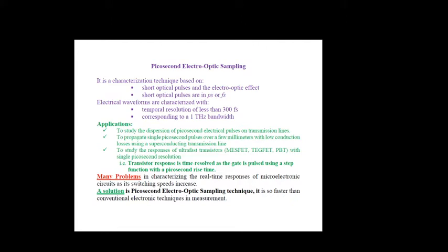Additionally, ultra-fast transistors have been tested with single picosecond resolution. That is, the transistor response was time resolved as the gate was pulsed using a step function with a picosecond rise time. Here there are three devices: MESFET, TEGFET, and PBT, that is, permeable base transistors.